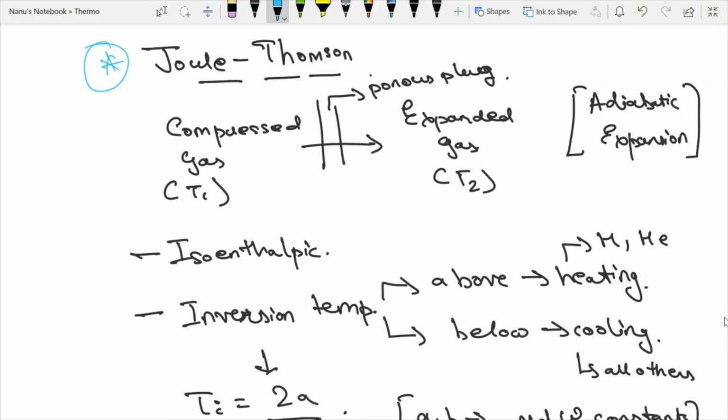So in short, the concept of Joule-Thomson is, when we pass a gas which is more compressed, suppose it's at P1, and it goes to P2, and in going from P1 to P2 it's expanding, so it's going from a more compressed place to a less compressed place through a porous plug. If a gas is passing like that, a change in temperature is noted, and it is an adiabatic expansion process. Adiabatic means no change in heat, and it's expanding, right? It's also an isoenthalpy process. What is enthalpy? Like del H is constant.